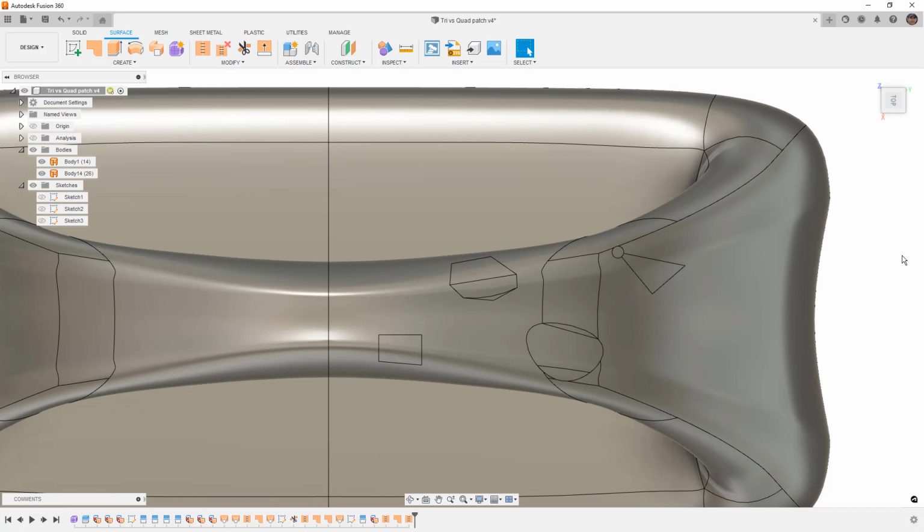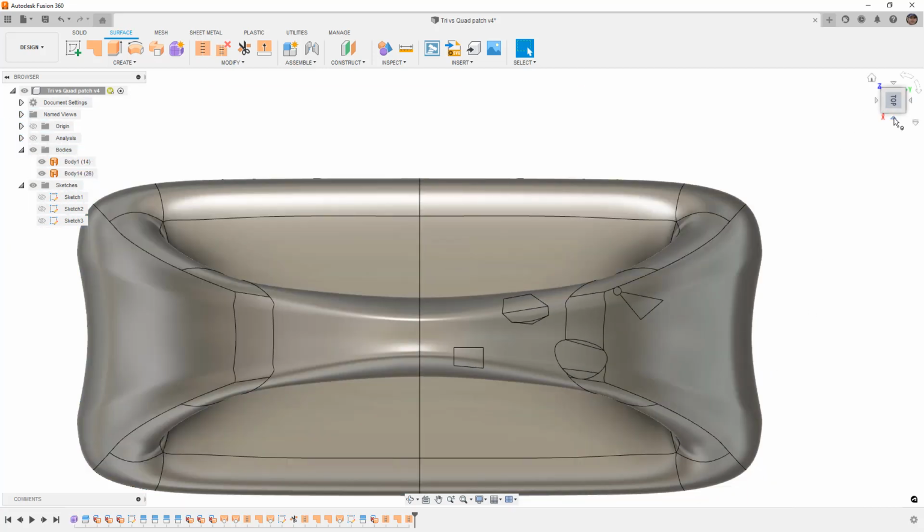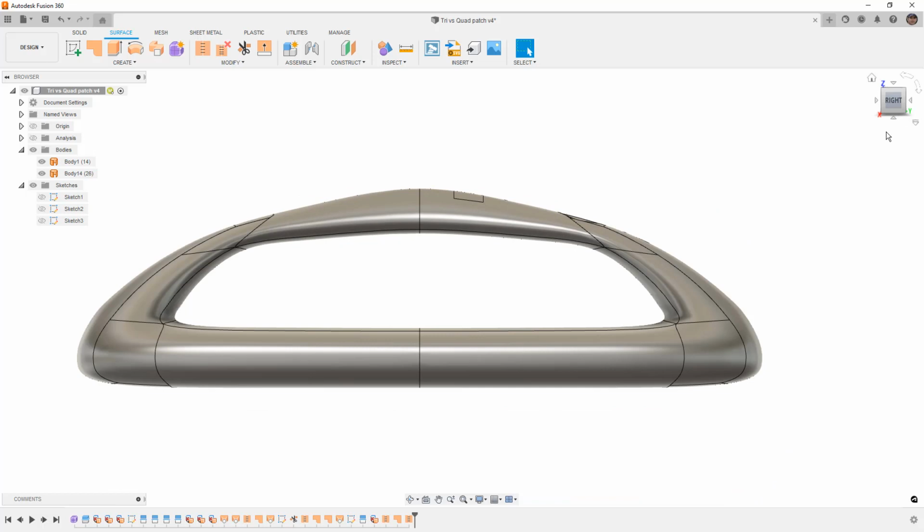Now, the last thing that I could potentially try here is to cut away this entire section and rebuild this portion of the design. Now, I can tell you that is easier said than done on this design, and that's because this design came from a form body. The form bodies sort of play by their own rules, and even though it's converted to a solid or a surface, it doesn't behave in the same way as generating that as a B-rep or a NURB surface from scratch.